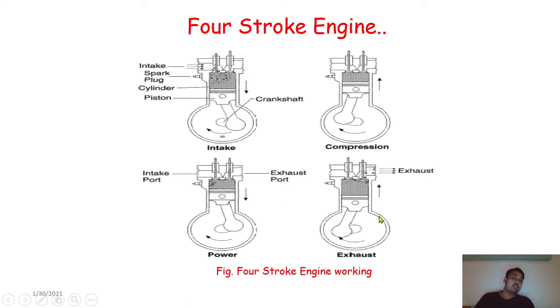So again, these two processes will happen within the next 180-degree revolution of the crankshaft, or half revolution, and similarly exhaust will happen in the next 180-degree rotation of the crankshaft. So suction and compression will happen in one revolution of the crankshaft, and expansion and exhaust will happen in the next one revolution of the crankshaft.